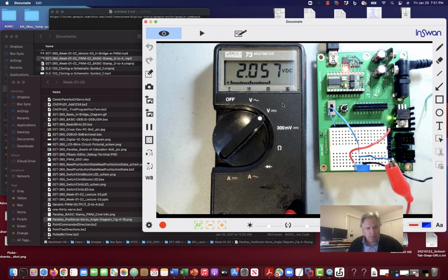And if you compare your rising sawtooth to some other analog signal with a comparator circuit, then when the two signals are equal, when they switch, you can note that in your microcontroller, and you could have timed how long it took for that ramp to come up to the voltage in question, and made a determination of what that voltage was. That's called a single slope analog to digital converter, and they can be built pretty accurately,